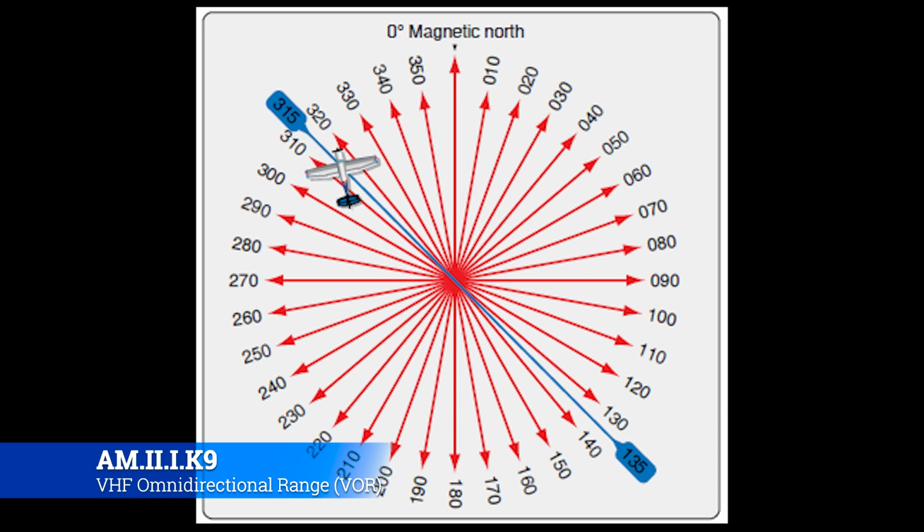Now they also have an identifier that you can tune the nav radio into. So you'll go to your nav radio, tune to the frequency of the VOR, and you'll see it on the indicator. It'll kick the needle the right way and flip the flag that says either to or from. Then you can put your headset into it or select it on your audio control panel, however the airplane works, and it'll put out a Morse code. Whereas ADF was 2 digits, these are 3 digits, so you'll get a 3-digit Morse code beep that lets you know, hey, I'm listening to this station.